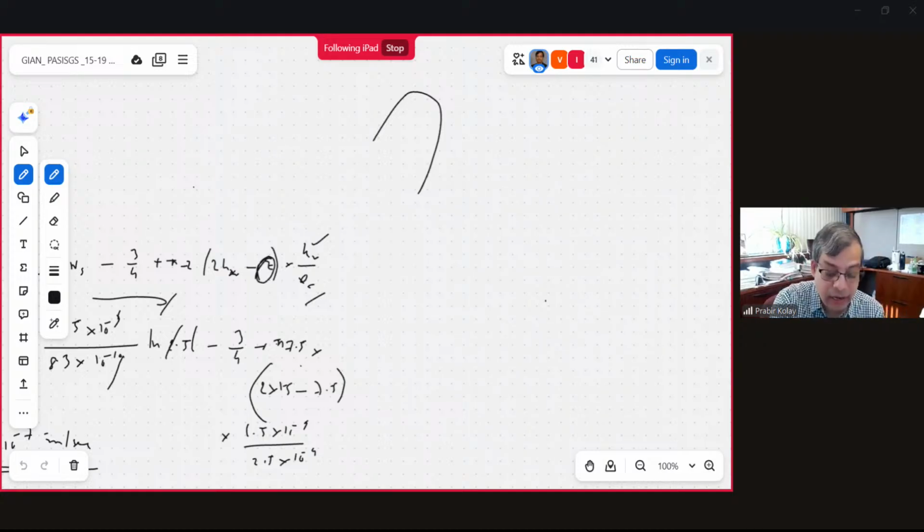The height here is 20 meters, so you just multiply with 20. You can calculate this easily, and you will get around 12.7 meters. That is the optimum penetration depth when using PVD with vacuum preloading.